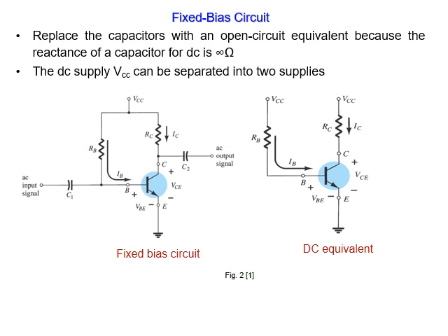Now, the first type of DC biasing we call fixed biasing. We need to number the names of the biasing. Now this is fixed biasing. How do we know it is fixed biasing? Because you can see that the transistor is connected through two resistances, RB and RC only. You see here the emitter is connected to ground, and the collector and base, rather than having two separate supplies, we connect them to one supply, which is VCC, and here the capacitor acts as a filter to separate between DC and AC. Okay, and usually for DC it's an open circuit, so no connection here.